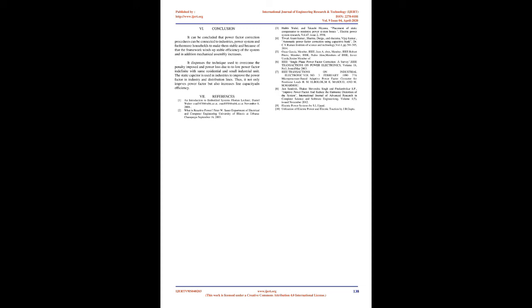If the current power factor is cos φ1 and the targeted power factor is cos φ2, then required kVAR equals P (tan φ1 − tan φ2). Capacitance, C equals kVAR/(2πfV²), where P is the real power in kW, f is the frequency, and V is the voltage of the power system.